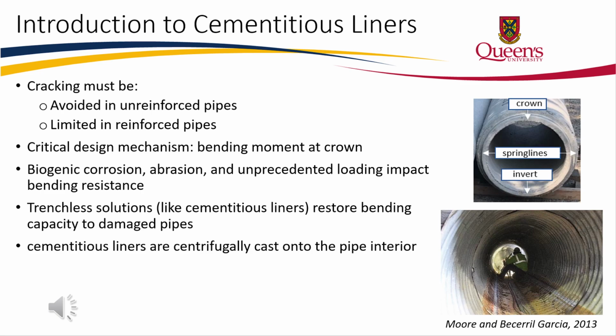Pipes are commonly rehabilitated with trenchless solutions as excavation-based methods of repair lead to increased financial and social costs. One such trenchless solution is the application of cementitious liners. Cementitious liners are centrifugally cast with a spinning head that travels along the interior of the pipe. Cementitious liners may also be applied by hand. The liner is applied to the interior of the pipe wall and left to cure until the admixture reaches an adequate tensile strength. Proper curing of the liner may require rerouting of stormwater prior to application.